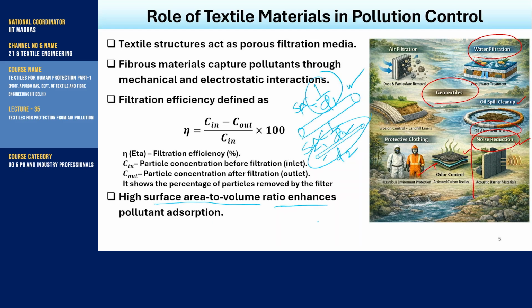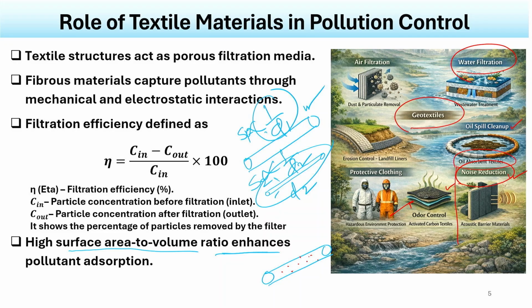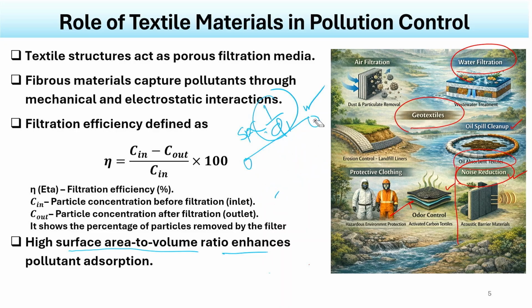and that will help in absorbing the pollutant. On the fiber surface, the pollutants are adsorbed. So, the higher the surface we can present to the pollutant, the more it will get absorbed. So, finer fiber will present higher specific surface area, that is why the filtration efficiency in case of finer fiber will be higher. So, by manipulating the fiber dimension we can also change the filtration efficiency.